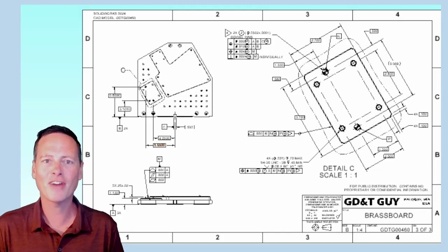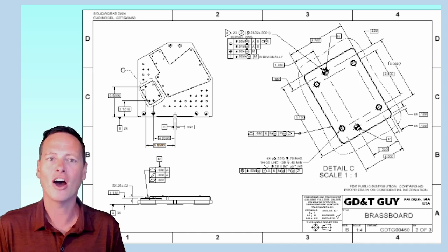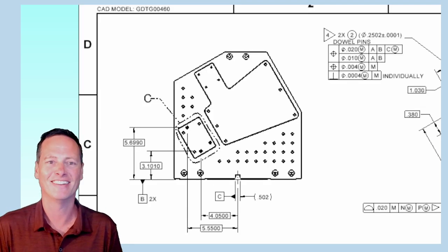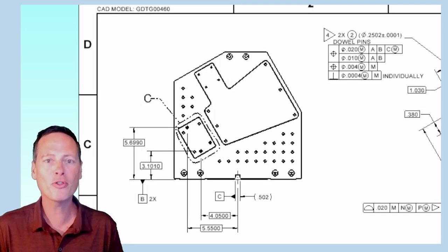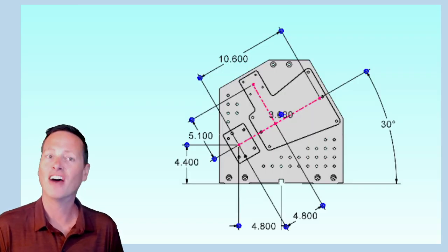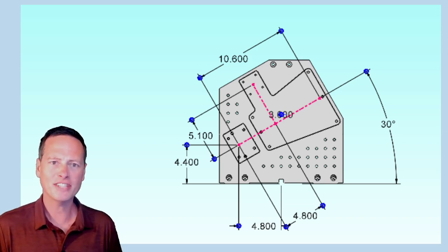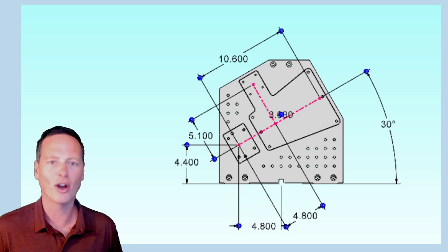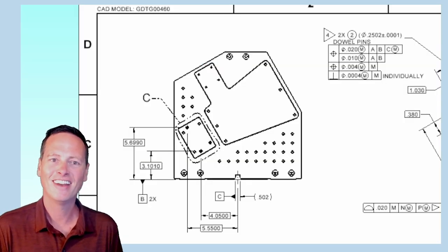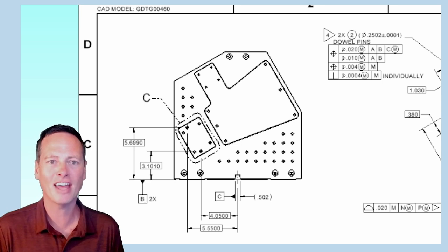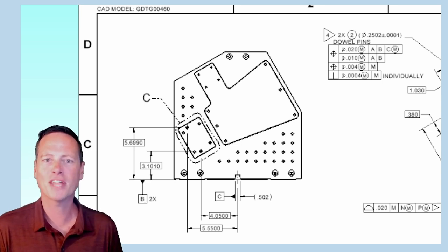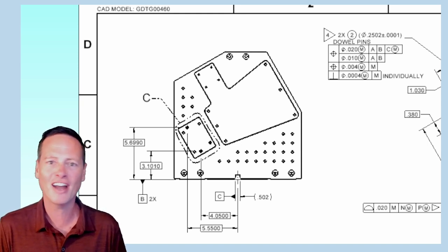So this is why I recommend an approach like I have here on GD&T 00460, and this is sheet 3. Here I give basic dimensions for both dowel pins in the interface from datum reference frame ABC. Now look, these pin locations trace back to some reference geometry in the CAD model. See how everything is at this 30 degrees or its complement 60 degrees? I think it could be possible to replicate that in this drawing view here with some center lines, basic angle, basic dimensions pointing to the intersection of the lines, etc.